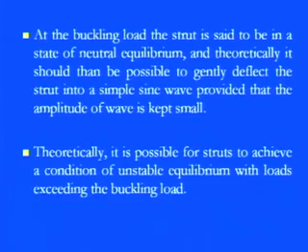So if we are talking about the theoretical, then it is always possible for a strut to achieve a condition in which unstable equilibrium is there when we exceed the buckling load. Because once we go beyond that, we never know the prediction of how these layers will behave under this exceeded buckling load. So we can say this is an unstable equilibrium phenomenon if you apply the load beyond the buckling load.